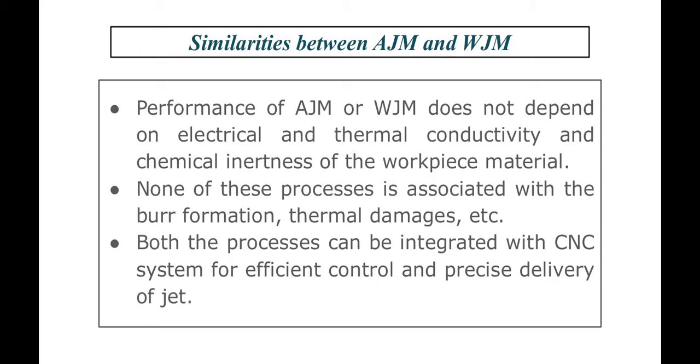Then the next similarity is that the performance of abrasive jet machining or water jet machining does not depend on the electrical and thermal conductivity and chemical properties of the workpiece material. However, several mechanical properties like strength, hardness, etc., influence the process capability, as we know.